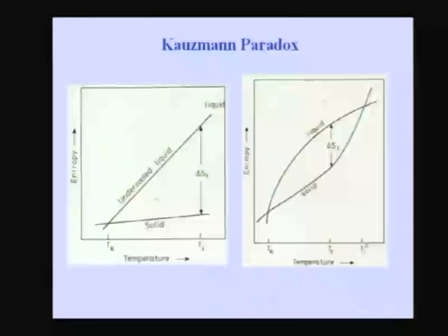So, what you see here is that when a solid is melting, the surface is already there, so you do not have to create a surface. So, usually the solid does not need any superheat. In the case of entropic catastrophe, as you keep on increasing the temperature, the entropy of the solid increases so rapidly that at a particular temperature beyond the melting point, and this happens definitely beyond the melting point, because you can see Tf is the freezing temperature and Tsi is beyond the freezing point, at that temperature the entropy of the crystal becomes the same as that of the liquid, and if you cross the temperature, its entropy becomes higher than that of the liquid.